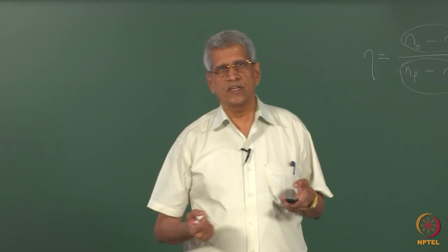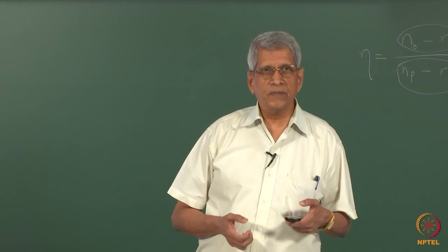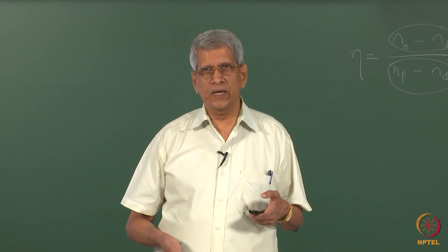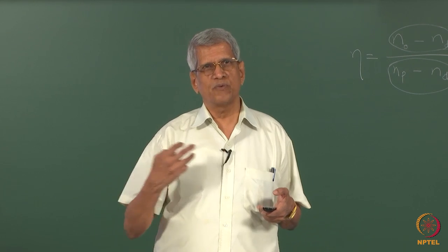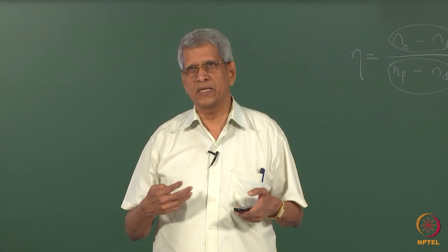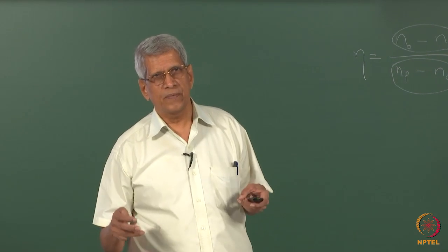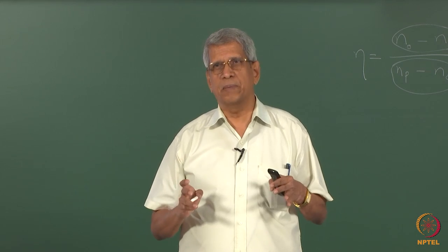What is the consequence of it in terms of choosing a material, especially for creep behavior? We would like to have a material that is ordered. We say that diffusivity comes down. This is the reason why diffusivity comes down in an ordered material and the creep rate will be lower. Is it clear? So this is a type of defect which is seen only in ordered materials.